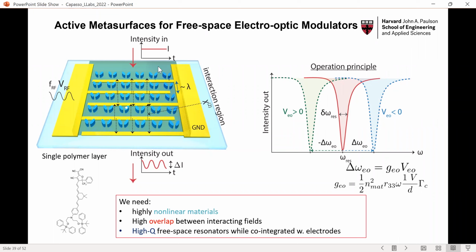And the idea here is you have an interdigitated structure, and you have nano pillars. In this case, they're of silicon. I'll describe them later. And this is embedded in a matrix of an electro-optic polymer, which has an extremely high coefficient. So the idea is to make a modulator. First of all, in order to get this high electro-optic effect, you have to pole these organic layers, and you do that by applying a static field between these interdigitated electrodes.